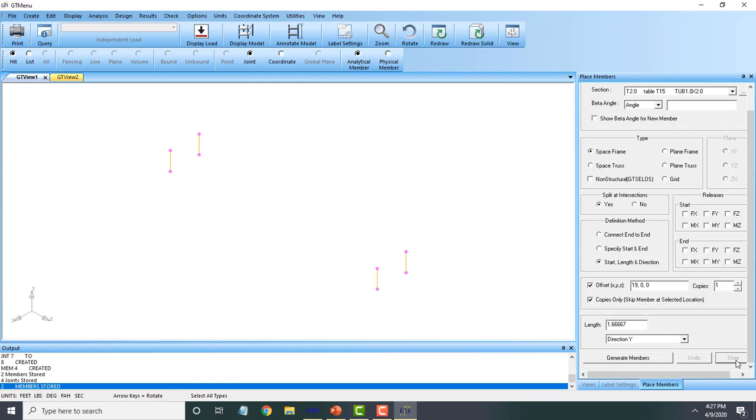Next thing that we're going to do is draw some connecting members. For that, I'm going to go to the PDF document on page number 66 of that document. Now we know how to draw members. There's an exercise problem that tells you to create additional members and delete some members. So what if we wanted to delete a member that I just created here? Very quickly you can do that. And what the exercise tells you is create an extra vertical member as shown below, using the knowledge that you've gained so far. And what they're telling you to do is basically draw an extra member.